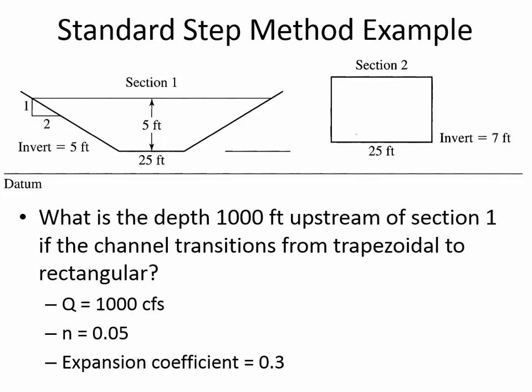Okay, so the starting point for this, just like the last example, is to calculate the normal depth, the critical depth, and diagnose the water surface profile so that we can guide our first guess of what the depth at the unknown section should be.